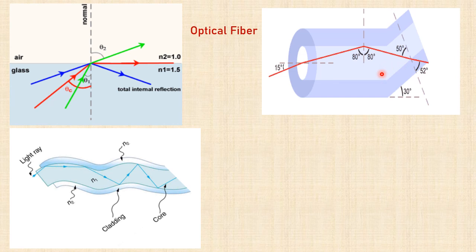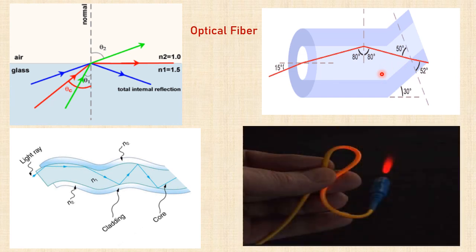So there are such bending losses in an optical fiber. To give you a clear understanding, let me show you. You can see this particular region where light is getting lost to the surroundings. So this is how you get these bending losses in an optical fiber. Whenever there is some bending loss in an optical fiber, there is a change in the intensity of light coming out of the fiber. We take this principle and frame